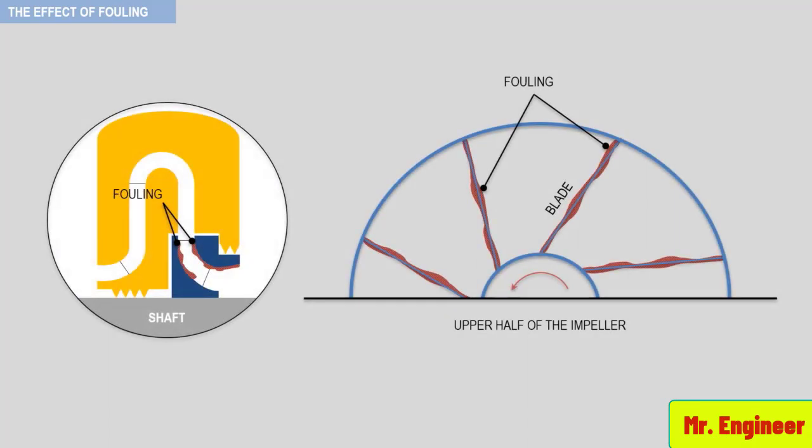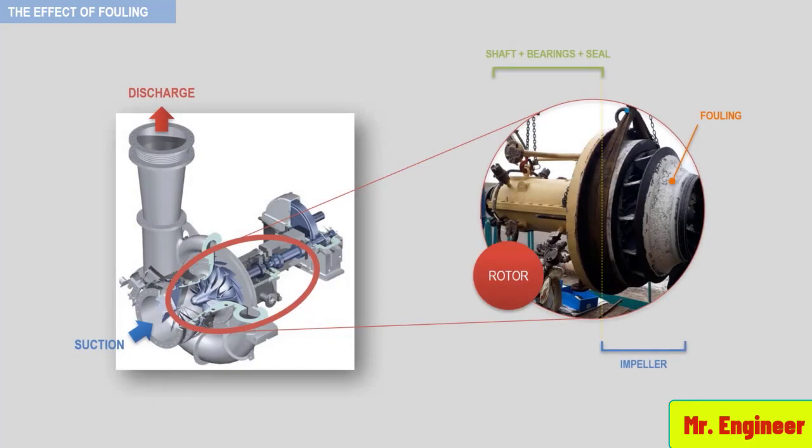As discussed in a previous video, the mechanism of fouling involves non-uniform accumulation and removal of debris from the impeller or blade row, which results in a performance design change in the mass accumulation of the foulant on the impeller. This action will change the rotor balance and the phase angle of the imbalance.